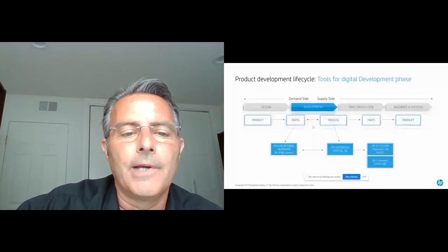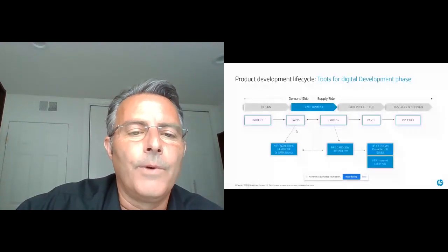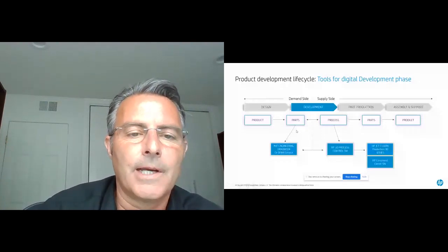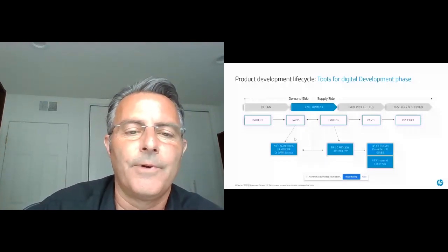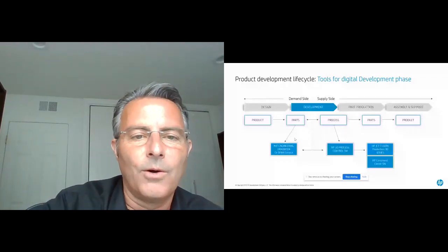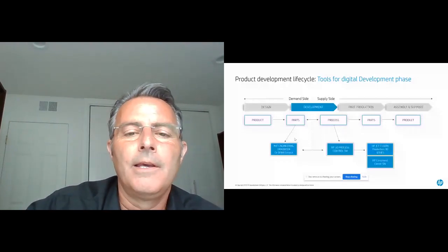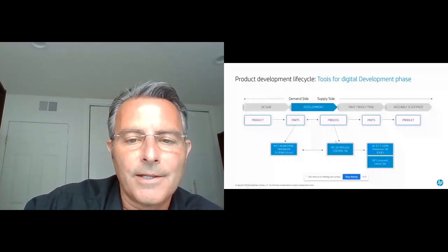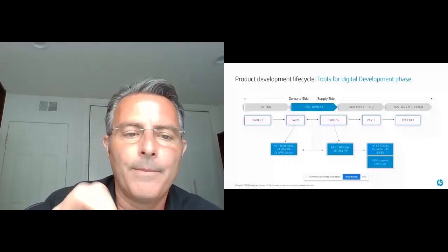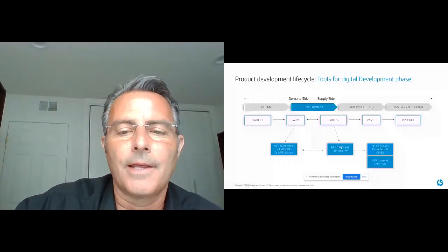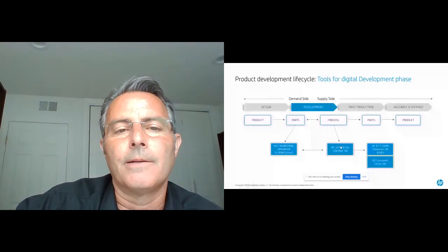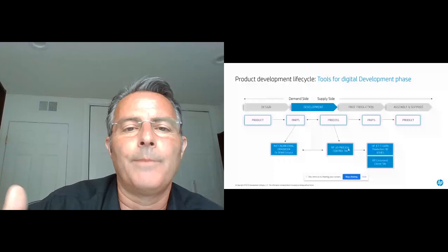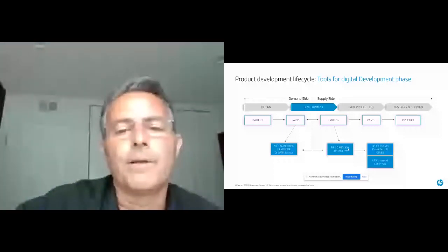Now, what we've done at HP is this. We've published our design rules for the multi-jet fusion technology in a handbook, which is available and free, so that the designers know what rules they need to follow for our process. For the process engineers on the right-hand side, we've given them process control software so that they can tune the parameters around the parts that they have in mind, and then you can go into production. Okay, so this is the first step, the final part manufacturing quality that people are looking for.